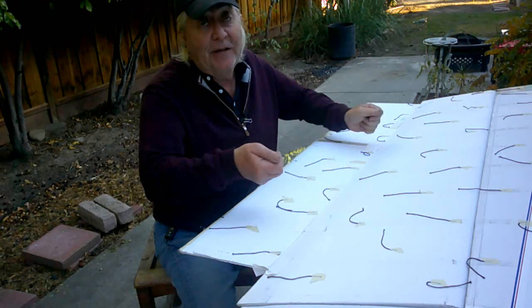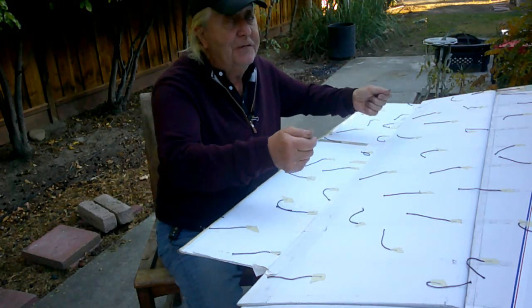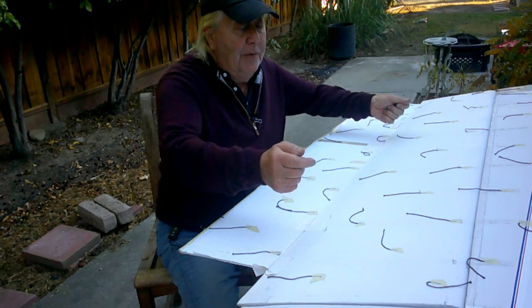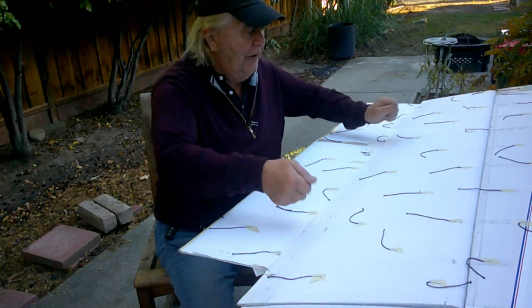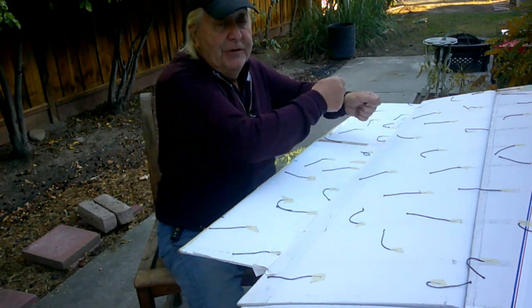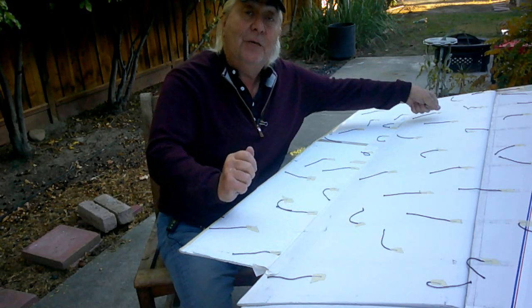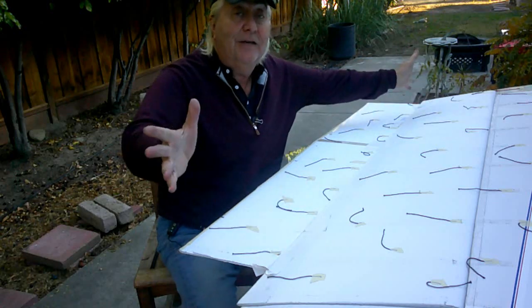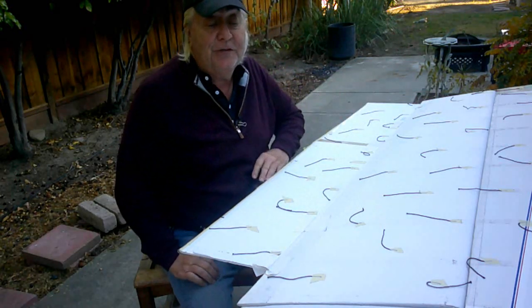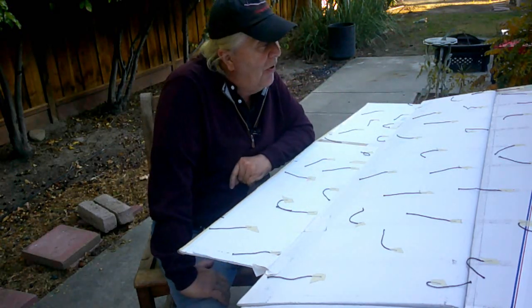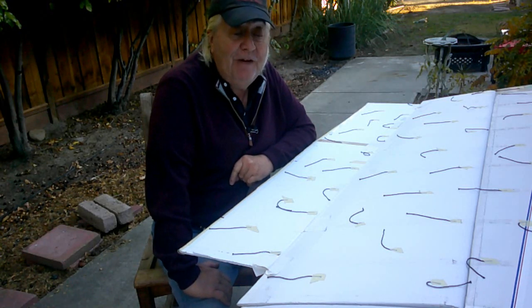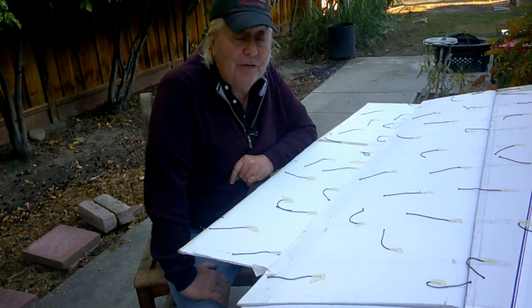And you might be saying, hey, what about the twist? What about the washout? But as you've seen with my D-tubes, before you put the shear web in, they're completely flexible like this. So you can just build constant chord and twist it this way for one wing and twist it the other way for the other wing and glue it down, and it'll stay that way, especially if it has a couple of nose ribs in it. So now we don't need to make as many molds. Well, there are some advantages to this concept of a constant chord flying wing.